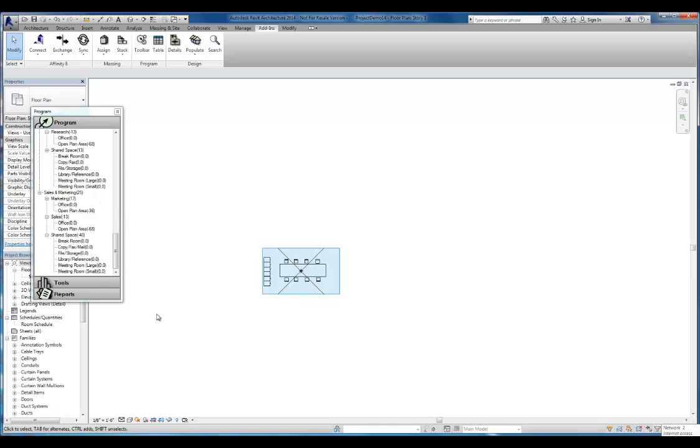Also, if you happen to have walls but you don't have the rooms, you can have it set so that this does not automatically group when dropped, and you can drag and drop the rooms themselves into the Revit model. But instead of dragging out a brand new room within Revit, you're dragging out a room that already ties to your program, and then you can start doing whatever design you want and don't ever have to worry about going back and forth between Affinity to create an early design, if you would like to do your design directly inside of Revit.